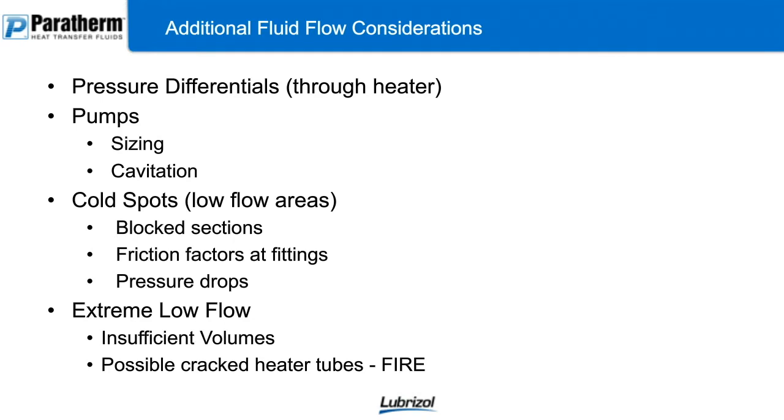Important flow consideration, your pumps. So sizing your pump, if you don't have a pre-packaged skid unit where the pump is sized for the heater size and everything else you're using, you need to make sure that you work with your pump manufacturer. Let them know what your fluid viscosity, your fluid density, all your fluid profile or properties are going to be. Make sure you size your pump correctly for the system that you're utilizing. You need to worry about pump cavitation.